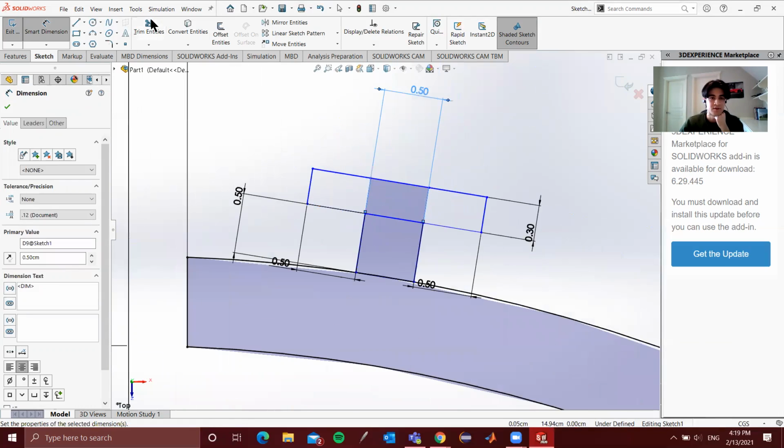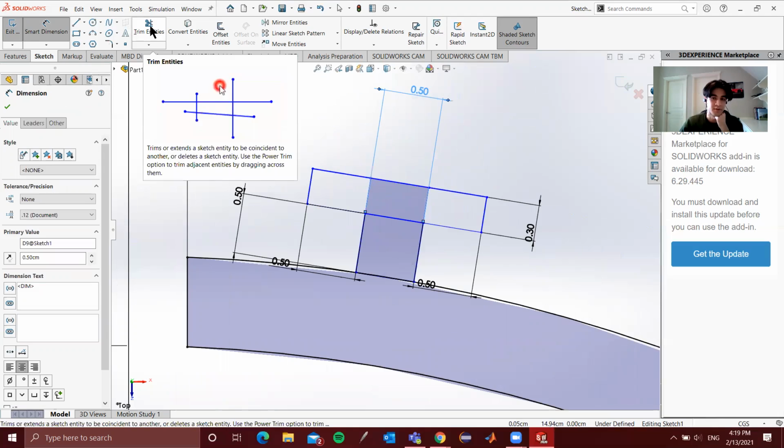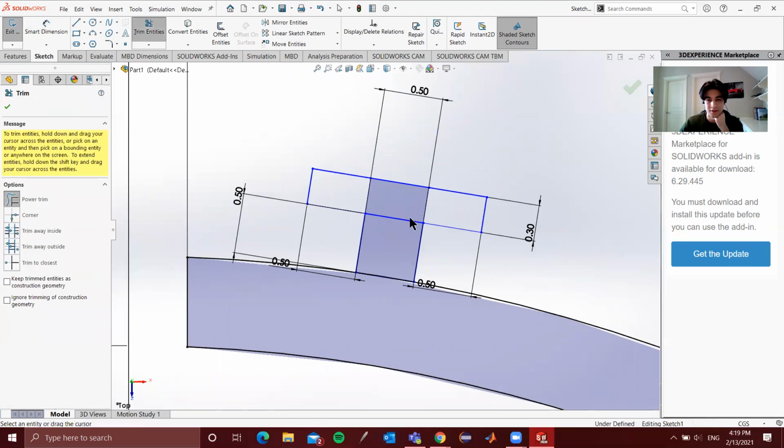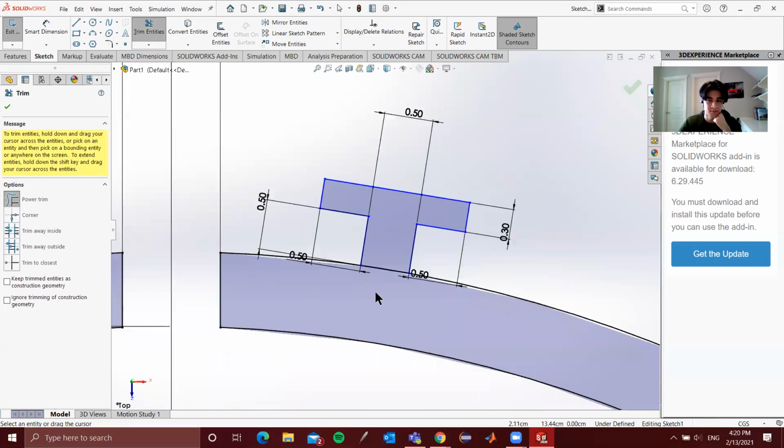Now it's not fully constrained, but first I'm going to get rid of a few lines. So obviously we don't want this line in the middle here. And the reason for that is because you can see these two sides are actually clear. So they're not filled within. So that means this contour is closed in the middle. And essentially there's these two different contours that are essentially separate from the main contour. So that's not something we want. So I'll get rid of that, get rid of anything in between, and that's one step.